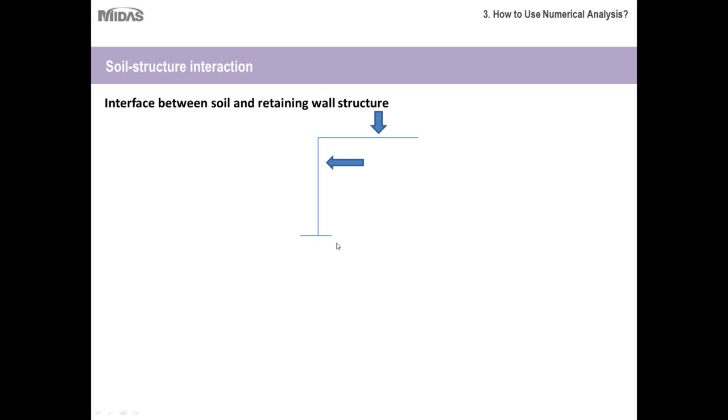So essentially it is nothing but a very simple stable system where you have one wall member, and this is the soil layer, and this vertical arrow is the surcharge, which may or may not be there, and this horizontal driving force, which is always there irrespective of the surcharge. This could be due to the unstable slope and the sliding wedge, or this could be due to the active earth pressure. So when these forces are acting onto the structure and you are modeling this